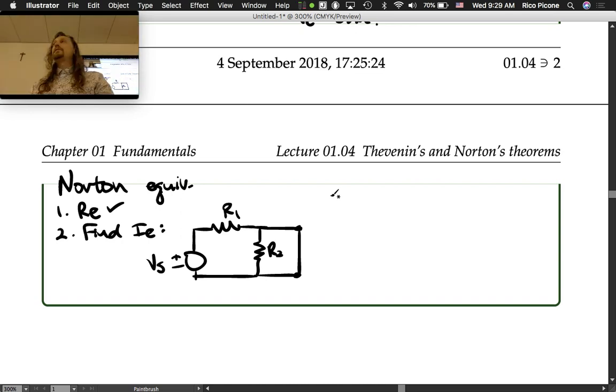You could actually solve for that by doing a parallel equivalent resistance here too, where the resistance of the wire is 0. So you'd have R2 times 0 divided by R2 plus 0. So that's 0 over R2, or 0. Okay.